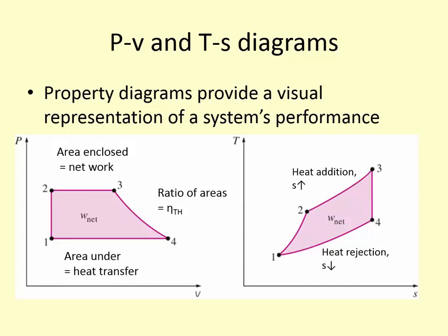So if we want to model an isentropic process, it would be straight up and down on the TS diagram, meaning the entropy is not increasing. Similarly, if we wanted to model on a PV diagram a process where the volume doesn't change or the pressure is constant, then we can model those as vertical or horizontal lines as needed.